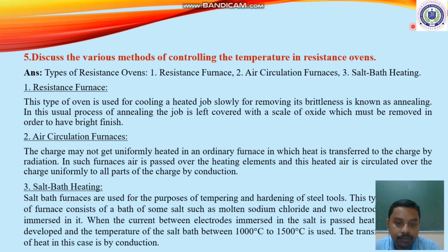Next is salt bath heating. A salt bath furnace is used for temperature treatment and handling of steel. This furnace consists of a bath of salt such as molten sodium chloride, in which two electrodes are immersed.